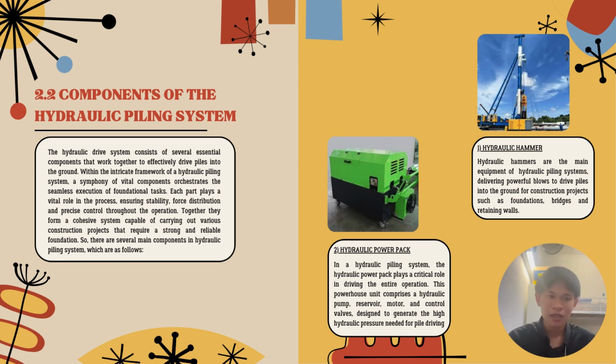Number two is hydraulic power pack. In a hydraulic piling system, the hydraulic power pack plays a critical role in driving the entire operation. This powerhouse unit comprises a hydraulic pump, reservoir, motor and control valve designed to generate the high hydraulic pressure needed for pile driving.